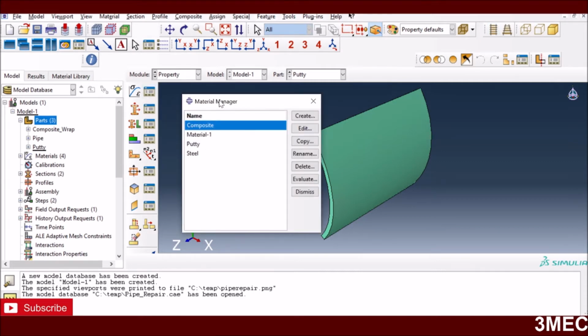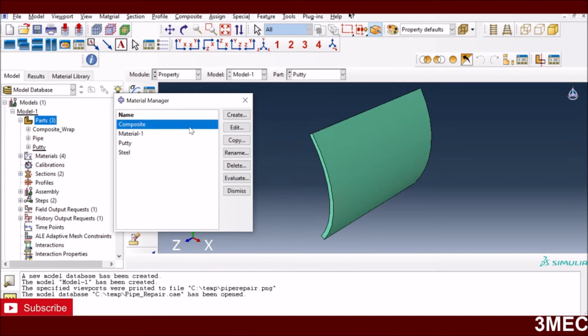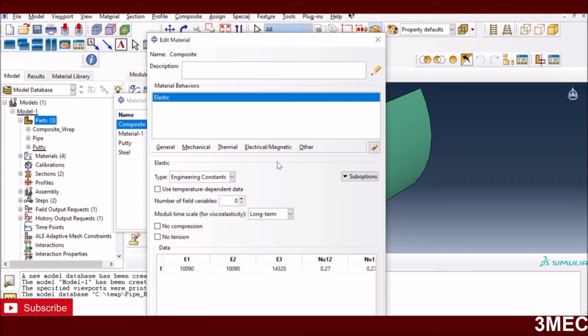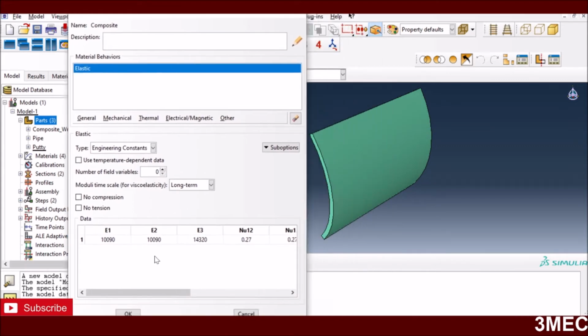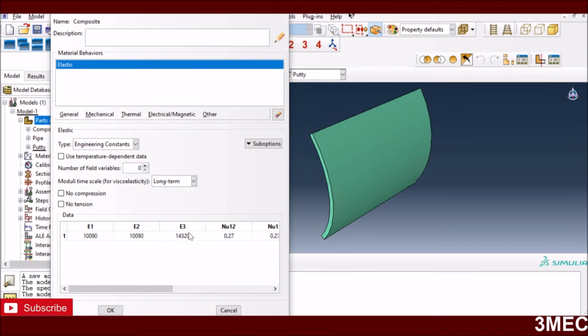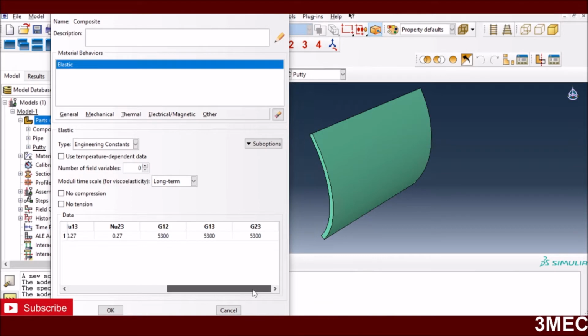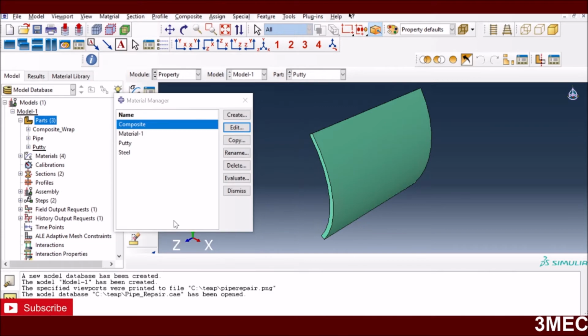Alright, for material properties, I have to define the material properties for each material. For composite, in this case I'm using the same properties as I have done before, and that is to define the elastic constants in all three directions because my fibers can be oriented in different directions, and also the Poisson's ratio along with the shear modulus. So again, I'm using the values which are provided by the user or subscriber and through that paper.